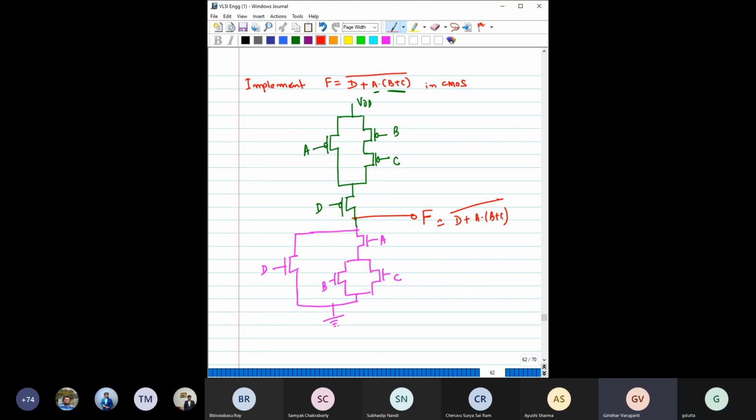So we can also draw this like at first we will draw B plus C whole bar, then put the output into another CMOS inverter, then from the output we will get B plus C. Then we will AND that output with A. Right, but then the transistors still exist. It will then be multi-stage, no? Yes, multi-stage means you can make it multi-stage, but if you make a single gate using multiple stages, then what will happen? You have this stage delay, right? Yes, it has to be calculated. Right. Okay.